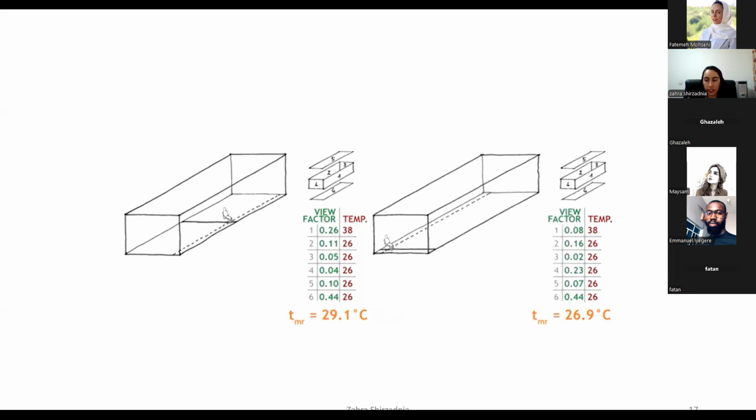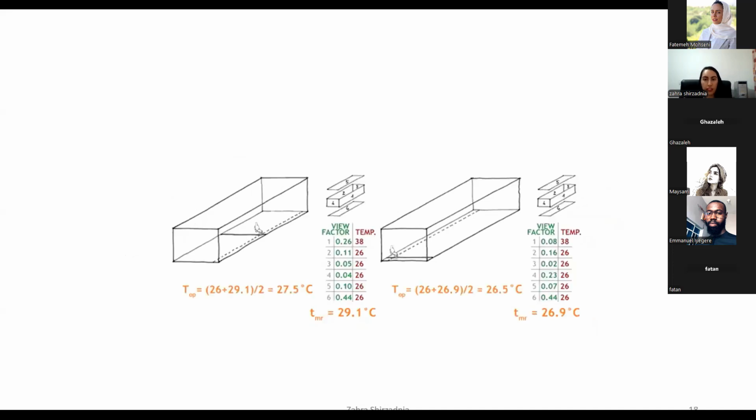If we are in an air-conditioned environment with 60% relative humidity and negligible air movement, the only environmental parameters affecting our heat balance are air temperature and mean radiant temperature. For this reason, a synthetic comfort index has been introduced: the operative temperature, defined as the mean between air temperature and mean radiant temperature.